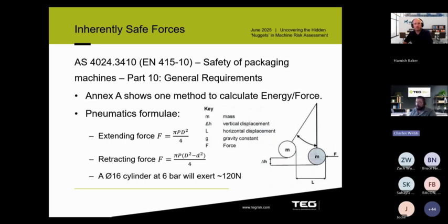Obviously, retracting, we're looking at the annular area of the piston, so with no piston rod. But what that means is now you can calculate exactly what force your cylinder will exert, but also you can now design your system with a cylinder that won't cause anyone any harm.